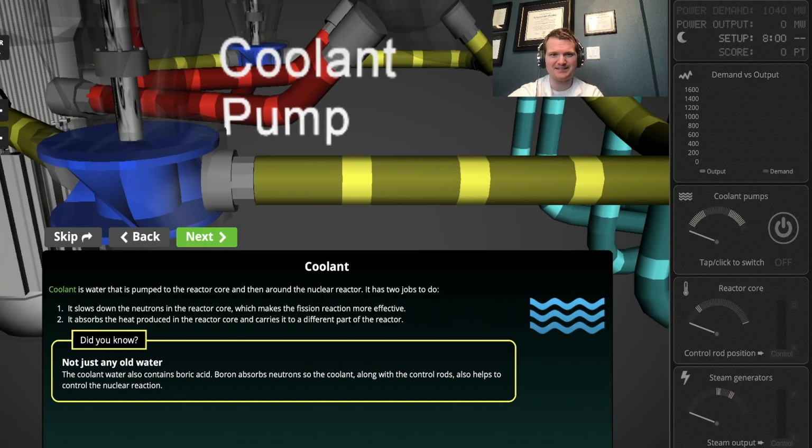And that's because of decay heat. The reactor will still generate heat after it's shut down. On the order of 1% and dropping logarithmically, but 1% is still a lot of over 3 gigawatts of heat for a typical pressurized water reactor.